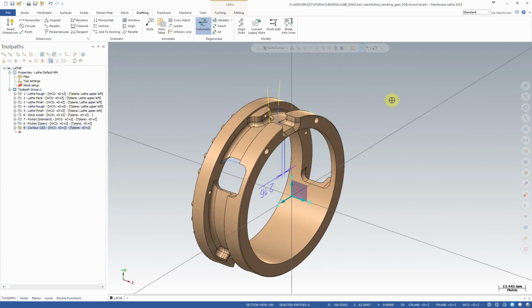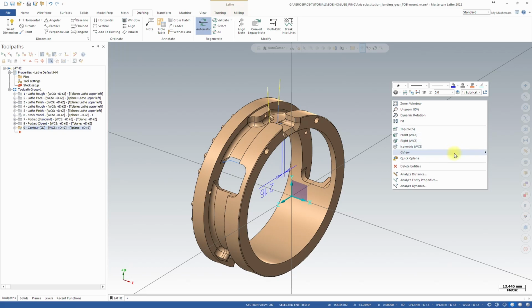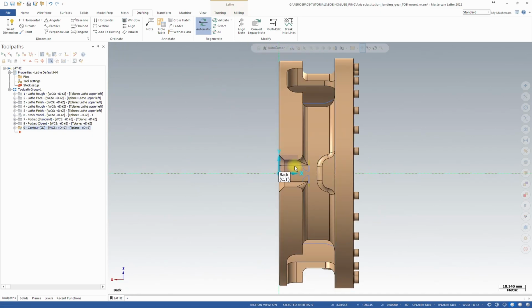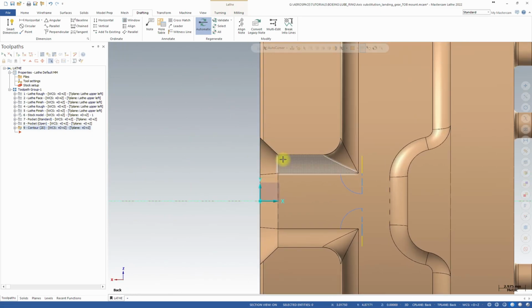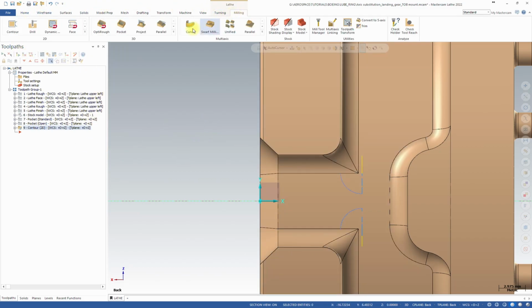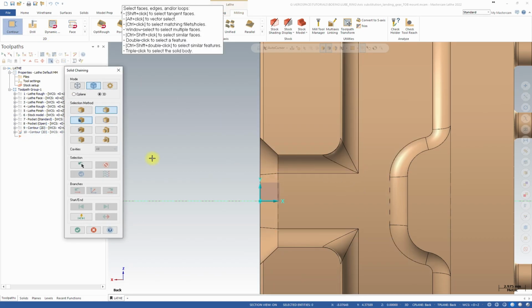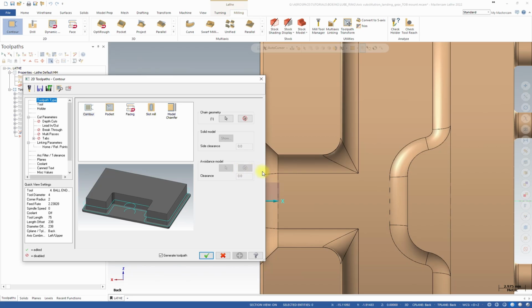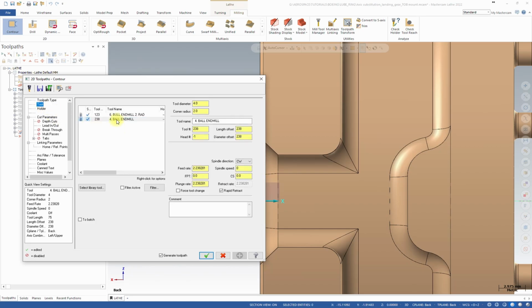Now, before selecting the operation, I'm going to pre-select a tool plane. G-view, and I'm going to use back, okay? So now, in this way, our walls are vertical, okay? That's fine. I'm going to set milling, contour operation, and I'm going to use single line, and with my compensation to the left, I want to go this direction and then this direction here. Okay, as a tool, 4 mil. I'm going to ignore that, it's just to show you guys.